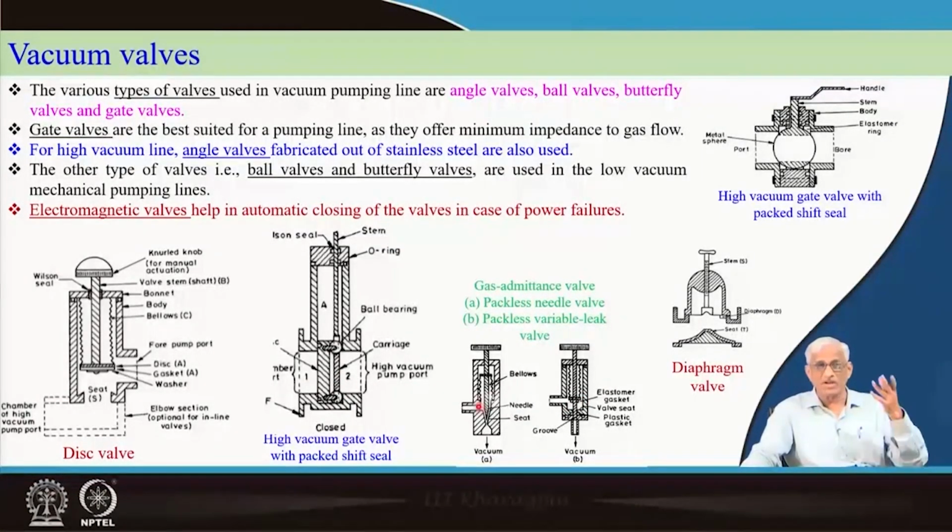Similarly, needle valves are required in semiconductor growth processes or various other chemical CVD processes, etc., where you will be letting in some gases for plasma processing, etc. So, they should be controlled. On one side high vacuum, on the other side almost atmospheric pressure, but very pure gases. Later in vacuum metallurgical furnace design we will see what we mean by pure.